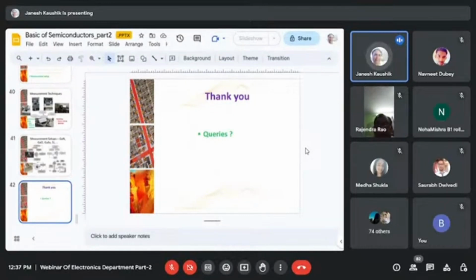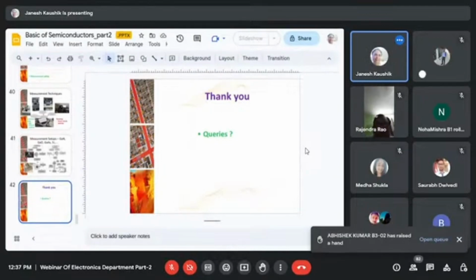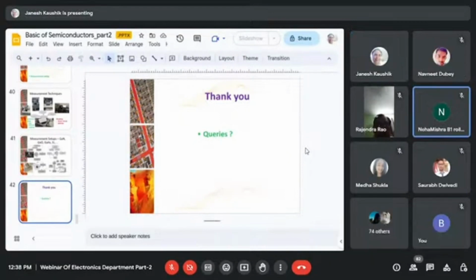And another thing which I explained: the moment a native GaN substrate is there, and you use an n plus doped layer at the top AlGaN surface, then there is a chance we have controlled surface states in the ungated region, and we will control this radiation effect in the virtual gating region, and then I hope that will solve the problem. But it will still take time. Hope I answered, Neha. Thank you so much.